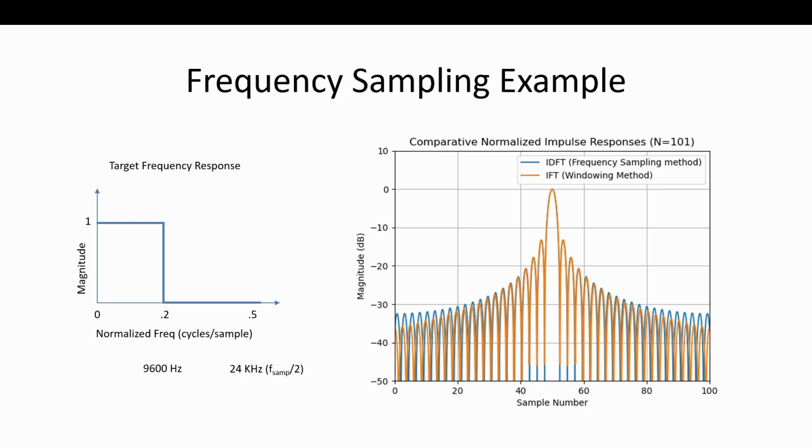If I take this desired frequency response, and there's 100 samples here, or 101 samples, so what did that mean? I filled this, and the FFT is periodic, so the 0.5 to 1 would be a mirror image of what you saw from 0 to 0.5. That little detail we introduced earlier. So if you take those samples that you want, you take 101, sample it, and then you take the inverse FFT of that, the impulse response looks like this, the blue.